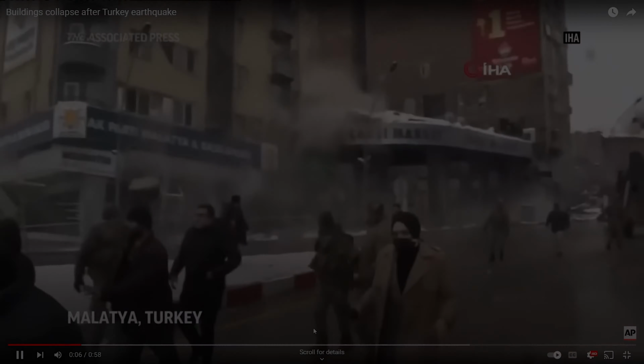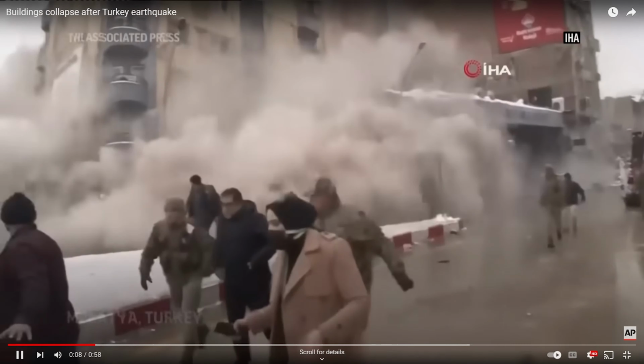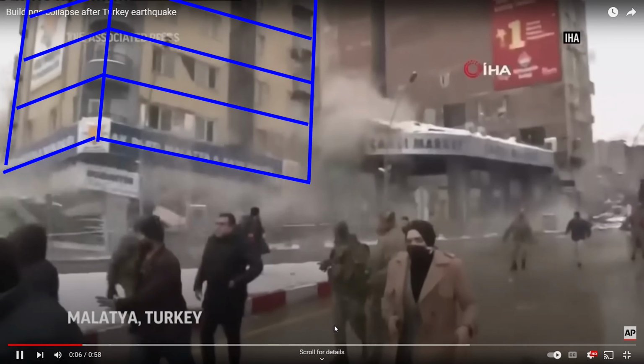Though a complete forensic structural analysis would be needed prior to making any definitive conclusions, a number of widely distributed clips of building collapses in the Kahramanmaras earthquake appear to show what looks like a weak or soft bottom story mechanism. In this first clip, which is reportedly in Malatya, Turkey, the bottom story of a damaged building appears to give out, leading to a collapse. As it appears, the top portion of the building is generally intact as the bottom story of the building gives way, causing it to lean to one side and fall on itself.